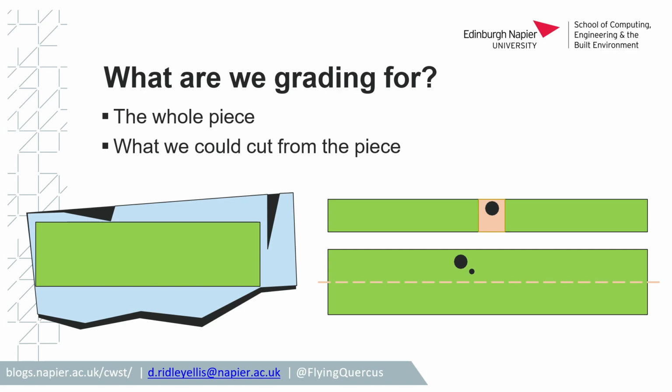So when we buy timber, we want it stamped on, or at least pay for it to have been graded. We cut it in half, or cut that board into 3 bits, bit with the knots drops away, and that would have to be graded separately from that, and there could be quite different grades, to be honest.